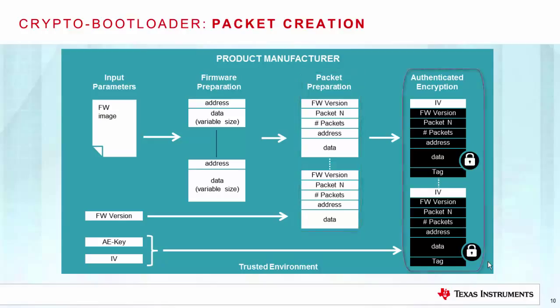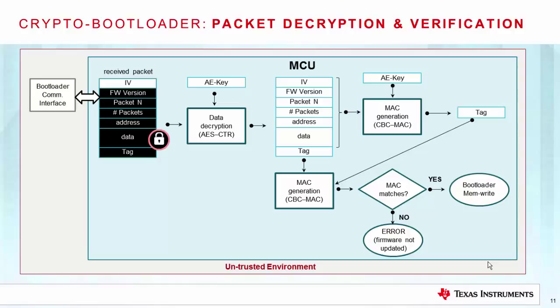The last step is applying authenticated encryption. A symmetric key along with an IV nonce are used to generate a tag for verification and to encrypt the packet. This is done making use of the NIST recommended authenticated encryption algorithm, AES-CCM, counter with CBC-MAC. On the microcontroller side, the encrypted firmware image is received by the bootloader communication interface.